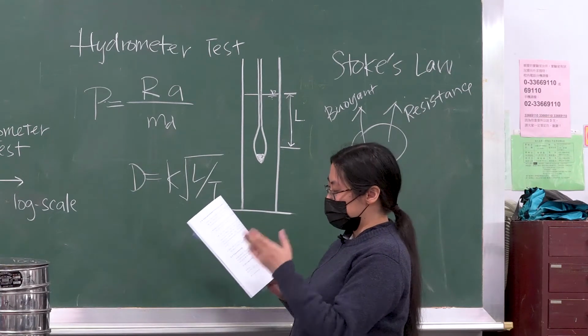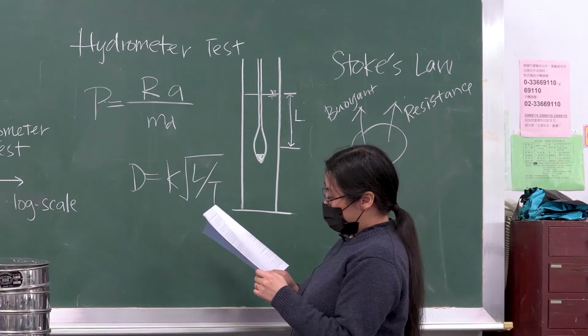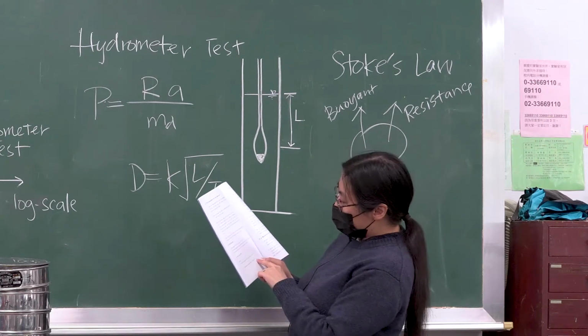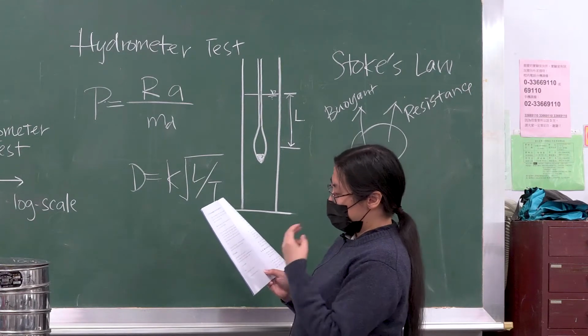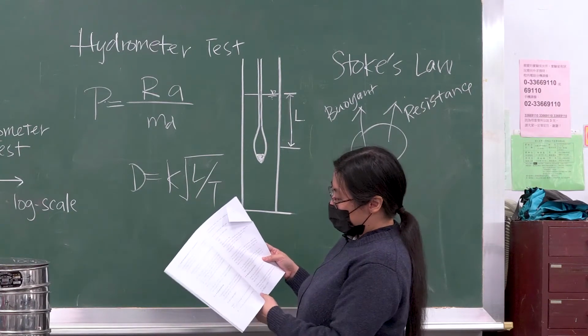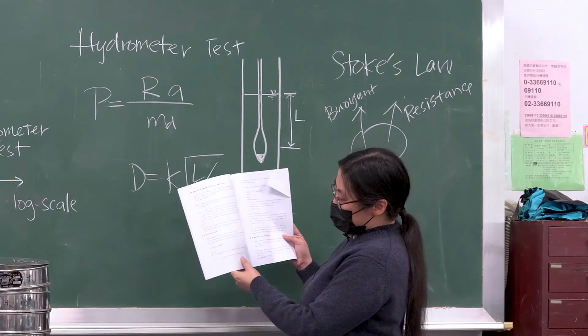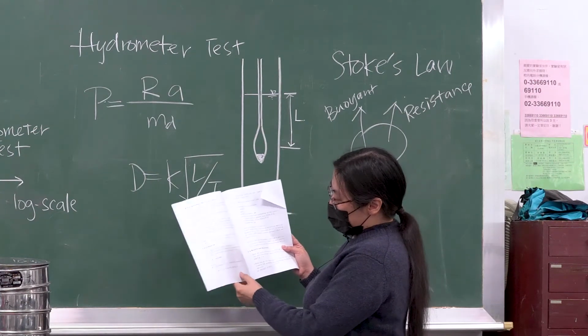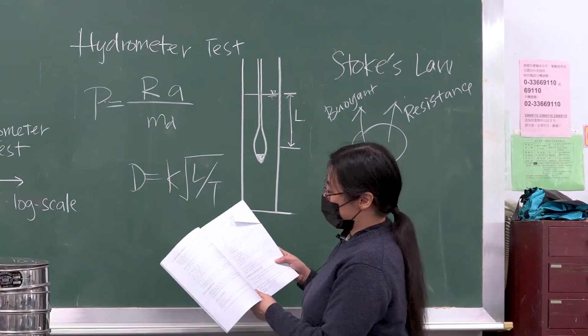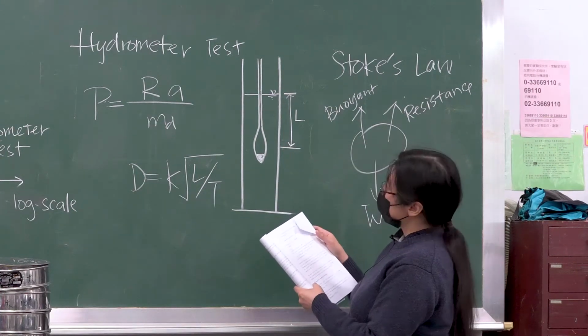When you have a cylinder of suspension with your soil particles, R1 is a reference hydrometer reading for the deflocculating agents. So basically you will need to take the difference between them, and then we will do that in a moment when we do the laboratory test.